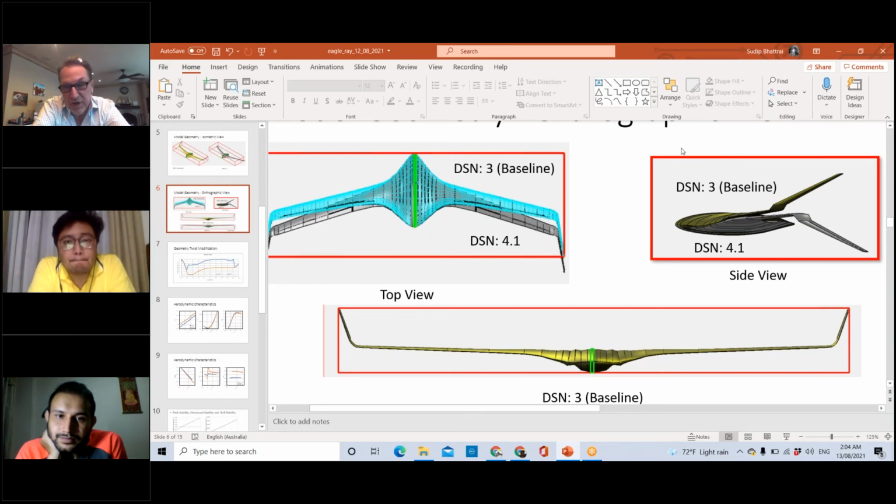Of course, you're recovering some wake energy by putting the propulsor in the wake of the airplane, as you guys probably have read about, called wake recovery, wake pressure recovery. So you're putting the thrust back in where the drag was taken out, and that means that thrust minus drag can be set to 0 with less energy. But you can also do that mid-span. You still get some of those benefits mid-span.